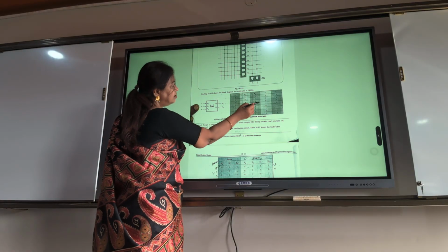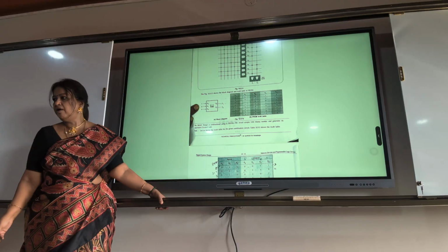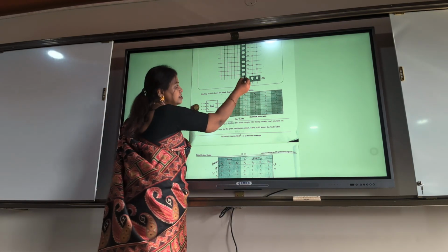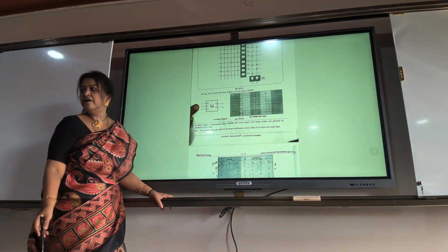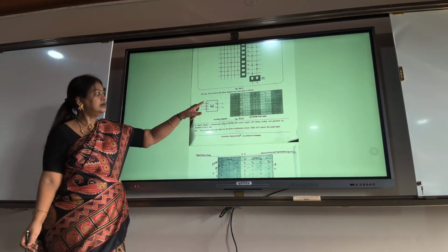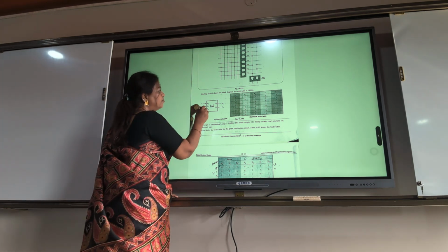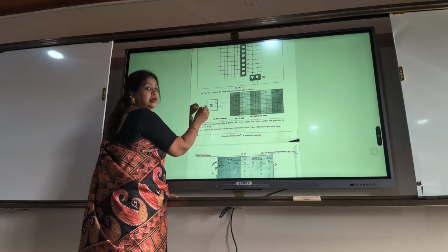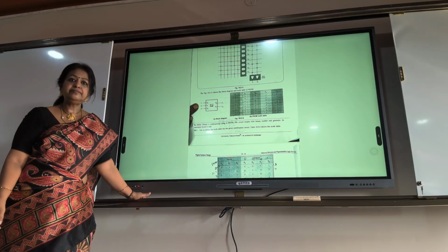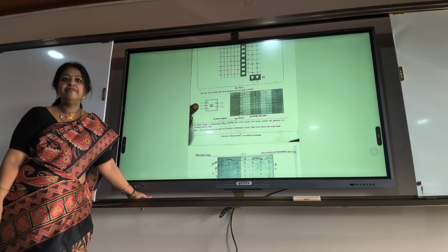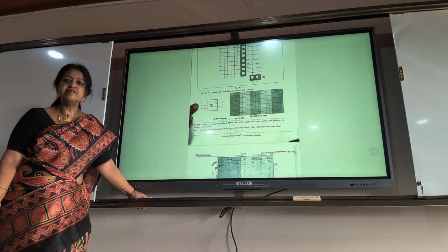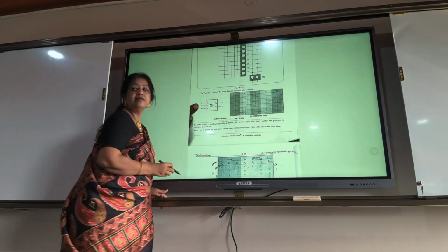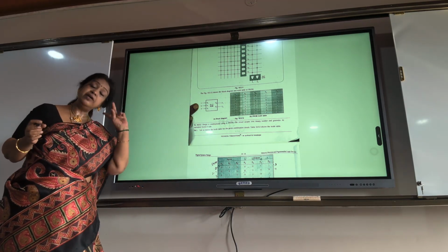So this is one. Take the truth table you have to draw. The truth table is the same as how we write the combinational logic circuit. F1, F2, wherever they are given, there you have to put 1 and the remaining should be kept 0. And then this is the ROM symbol. 3 inputs, 2 outputs. The size is 8 by 2. Size is very important. Size is calculated how? If n inputs are there, 2 power n is the address lines, and the number of output bits you have to see. So address lines by output lines will give you the size of the ROM.